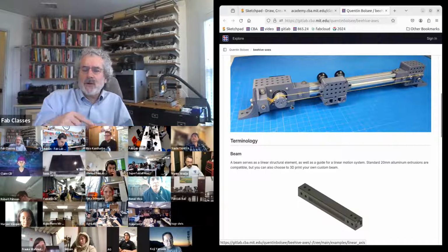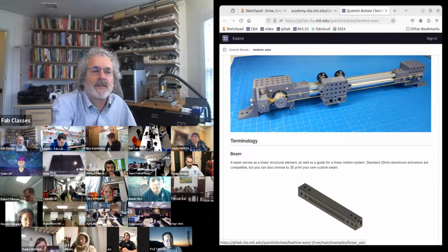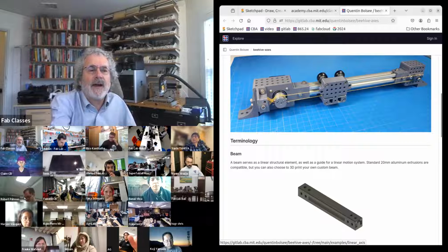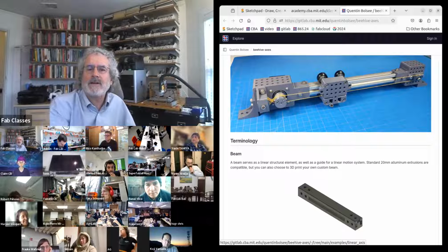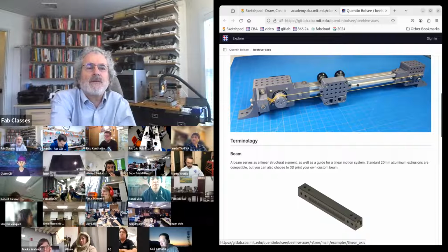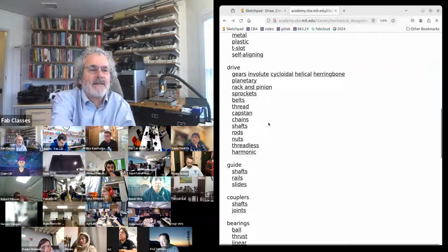The thread around the drum moves continuously, which is nice for smooth motion, but a single wrapping can slip. There isn't enough friction. So what the capstan drive does is multiple loops to increase the friction between the drum and the belt. And then what's handy is you can route the string wherever you want through the structure and cut off as much string as you want. And so that's what was running in front of Adrian for the capstan drive.